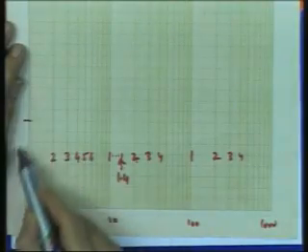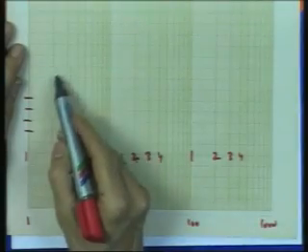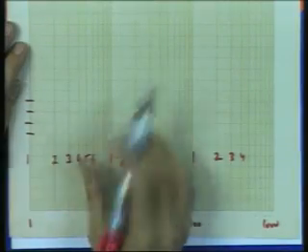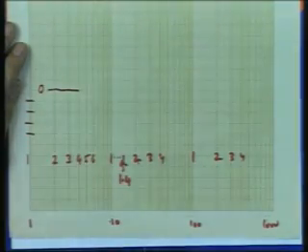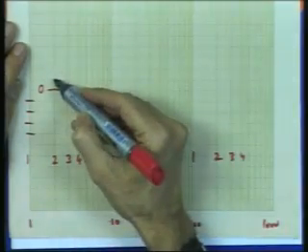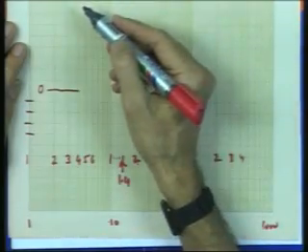What about the vertical axis? The vertical scale is uniform. For example, here each one of these corresponds to 1 centimeter and they are all uniform. So, if I choose my 0 dB line, and we have seen that you have to think about it a little bit and choose it appropriately. Let us say here is my 0 dB line, then I have to choose a scale for the dB. So, I may choose let us say 1 division or 2 divisions or whatever as 10 dB.